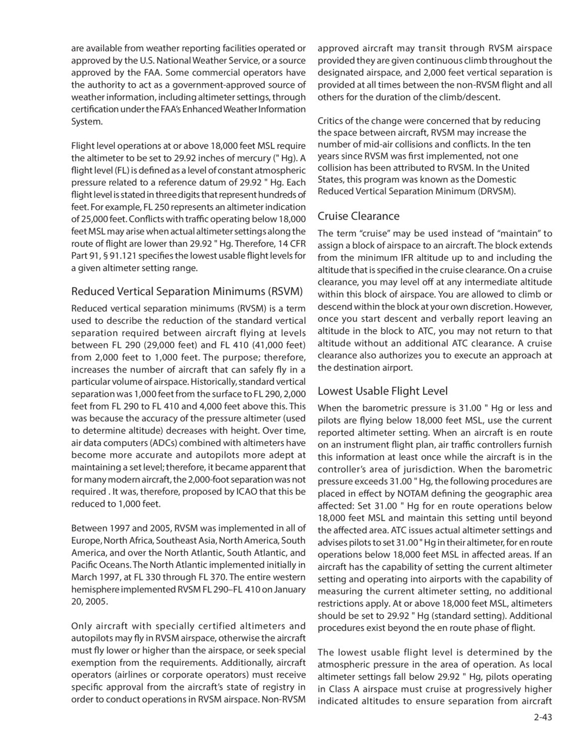Conflicts with traffic operating below 18,000 feet MSL may arise when actual altimeter settings along the route of flight are lower than 29.92 Hg. Therefore, 14 CFR Part 91, Section 91.121 specifies the lowest usable flight levels for a given altimeter setting range. Reduced Vertical Separation Minimums, RVSM, is a term used to describe the